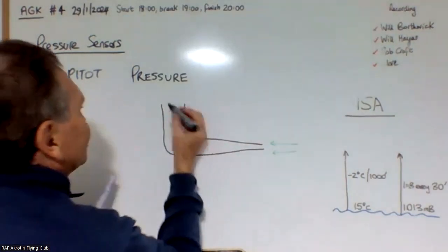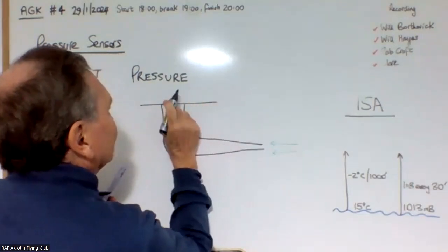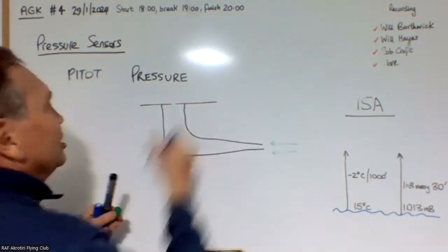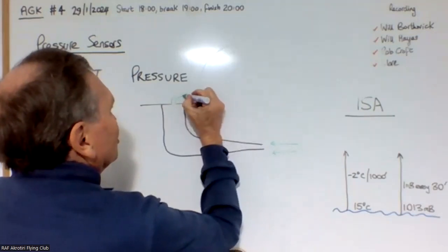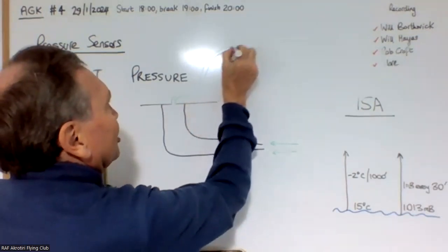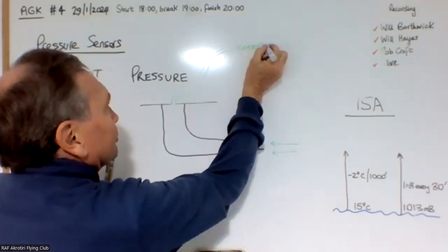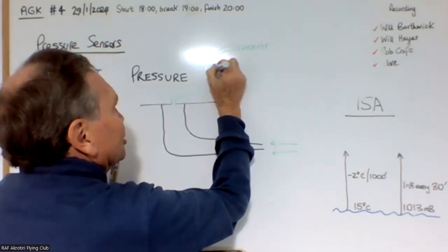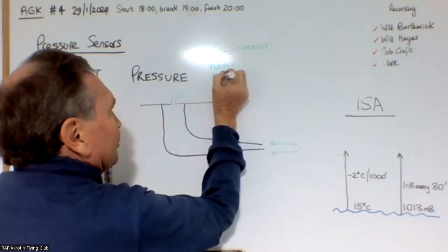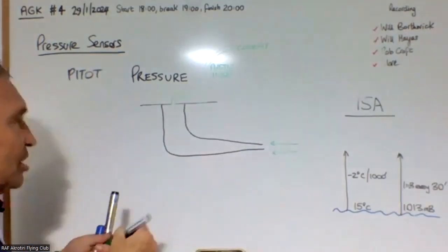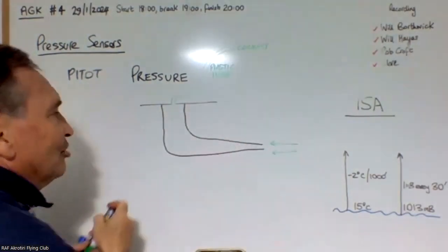And at the top of this, where it's bolted to the underneath of the wing, there is a tube here, another plastic tube. It heads off to your cockpit. A little plastic tube. And obviously the pressure inside here goes up the faster you go.